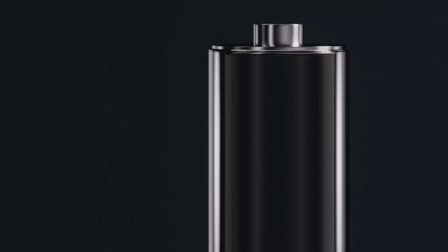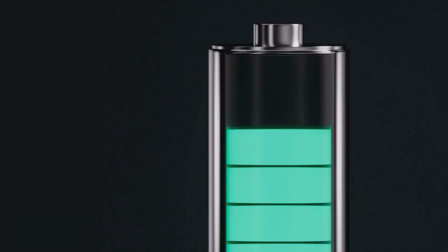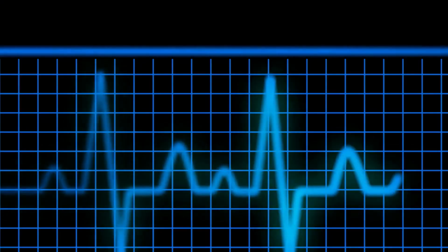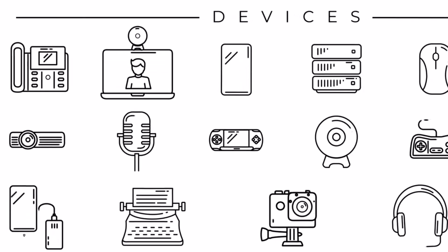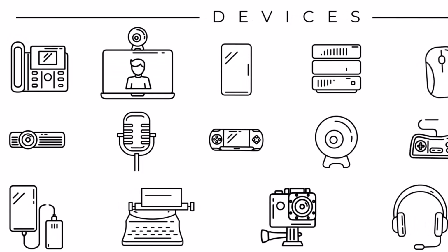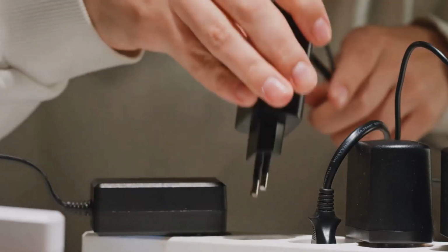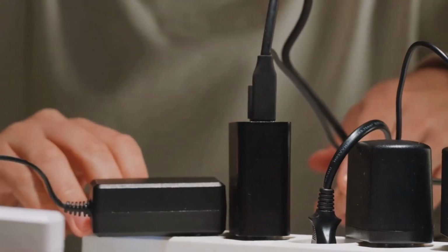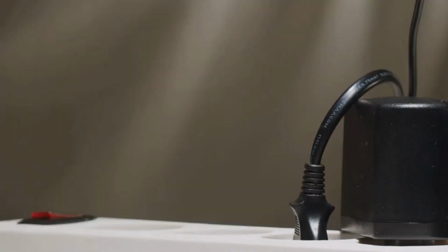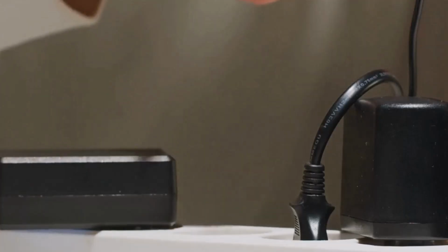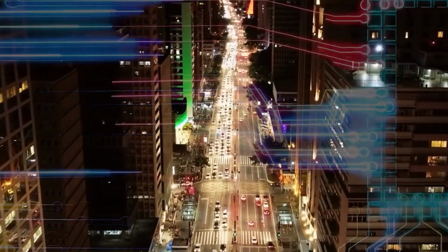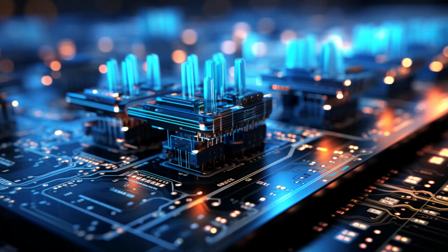The benefits of full-wave rectification are huge. The efficiency is doubled because we are no longer wasting half of the power. The output is more consistent and easier to smooth, leading to a higher quality power supply. This makes full-wave rectification the standard for almost all consumer electronics. The power adapter for your laptop, the charger for your phone, the power supply inside your television, they all rely on full-wave bridge rectifiers to do their job reliably. It's a brilliant piece of engineering that powers our modern world.